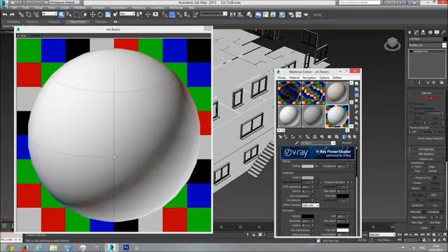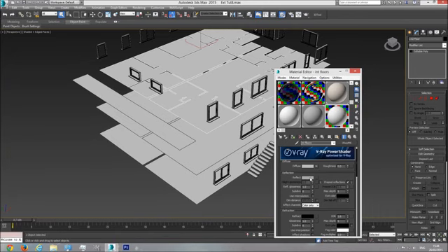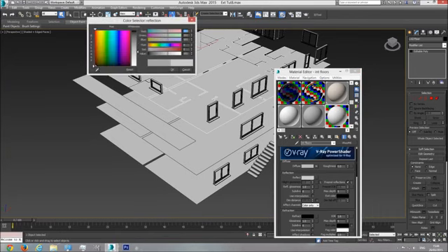It works like glass. If you think about it in real life, when you look straight on glass, you won't see as strong a reflection as if you look at a glass at 90 degrees. So this simulates this Fresnel reflection effect. So more reflective on the sides, less reflective in the front. So this is good for us. We need to make it just a little bit more reflective, like 150.